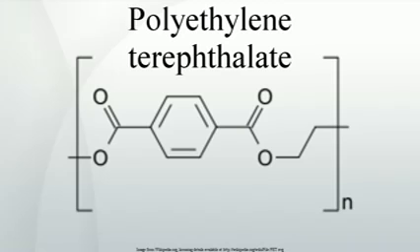The end group proportion shifts toward the direction of the COOH end groups built up through a thermal and oxidative degradation. The results are decrease in reactivity, and increase in the acid autocatalytic decomposition during thermal treatment in presence of humidity. Number of polyfunctional macromolecules increases.